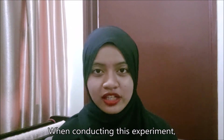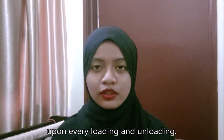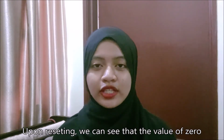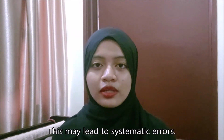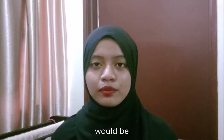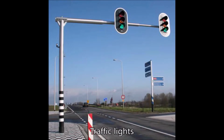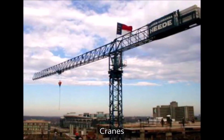While conducting this experiment, we need to reset the dial gauge to 0 upon every loading and unloading. Upon resetting, we can see that the value of 0 in the dial gauge does not stay and fluctuates. This may lead to systematic errors. Some real-life applications of cantilever beams would be balconies, traffic lights, aeroplane wings, shelves, cranes, and many others.